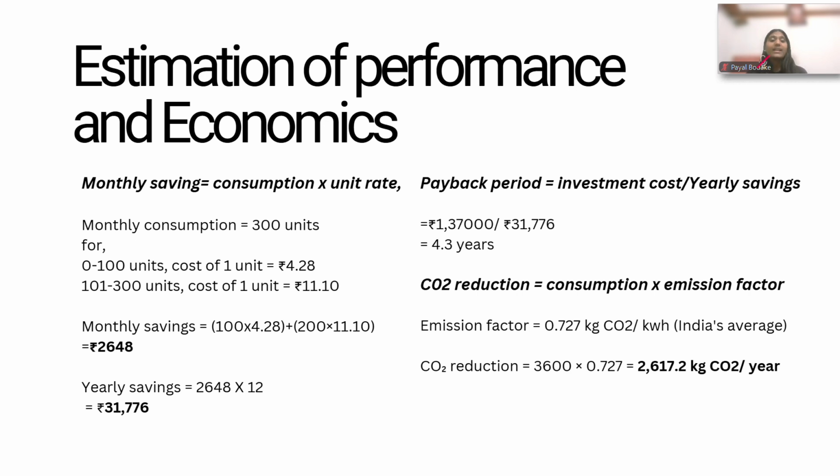CO2 reduction is equal to consumption into emission factor. Emission factor for India is equal to 0.727 kilogram CO2 per unit. Hence, CO2 reduction is equal to 3600 into 0.727, which is equal to 2617.2 kilogram CO2 per year.